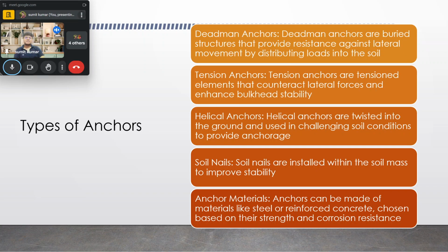And the types of anchor: first is the deadman anchor. Deadman anchors are buried structures that provide resistance against lateral movement by distributing the load into the soil. The second one is the tension anchor, an element that provides resistance to counter lateral forces and enhance bulkhead stability.